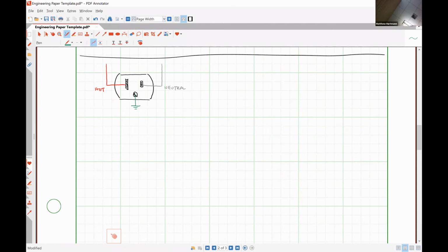In circuits involving a receptacle like this, the ground isn't really part of the circuit. So the neutral is effectively playing the role of ground, and you will often see that the neutral wire and the ground wire are tied together, or bonded together, outside of your home, literally through a grounding rod, which is a piece of metal that's stuck into the earth so that there is a reference potential for your system. All right, so you're saying that there is 120 volts